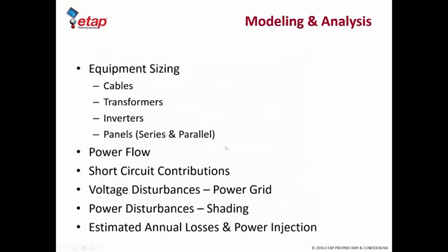As far as the modeling and analysis is concerned, we want to design the PV system, size various equipment like cables, transformers, and inverters, and perform various power system analyses like load flow, fault current, and arc flash calculations, and any disturbances that we want to introduce, such as a fault on the grid side, and look at the ride-through characteristics of the inverter, and the return on investment analysis, such as estimating the losses and the overall kilowatt hour or megawatt hour injection into the system.